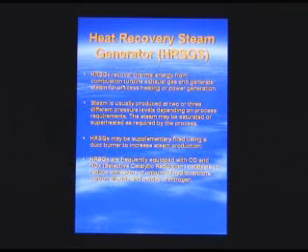Basically what this does is this takes heat from a turbine exhaust and will either use it or it will augment that with supplemental firing to produce a required amount of both saturated and superheated steam by means of taking the hot gas and exchanging the heat from the gas into a water coil, which basically flashes the water to steam. Heat recovery steam generators, as I say, can have a duct burner for increased steam production.